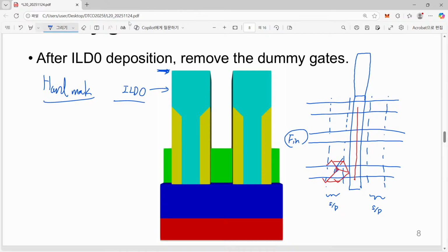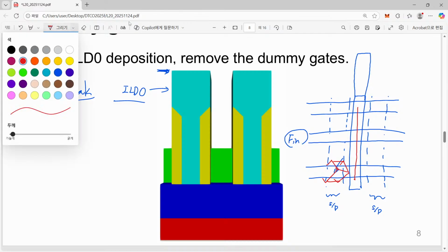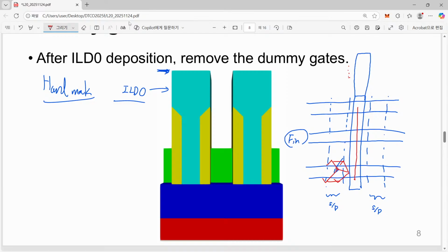I mean that previously we introduced a certain etching in this part, digging out ILD0 and ILD1, then we will see this metal line, and this metal line is connected from the top. That was the case. But you can easily understand that is quite a waste.